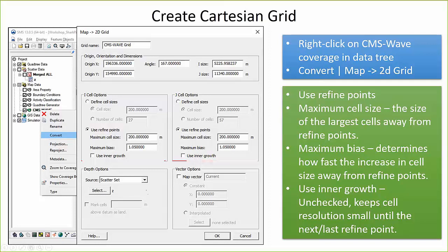And so throughout this process, you can build several grids, moving these refined points around a little bit to minimize the spacing. You just probably want to make sure that you have enough cells throughout your inlet to a specific distance in the back so that you can carry that information forward as it marches forward.